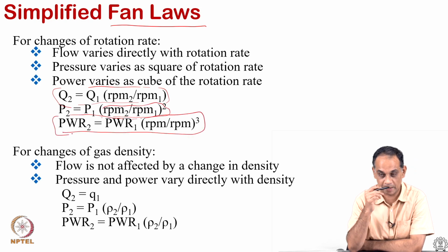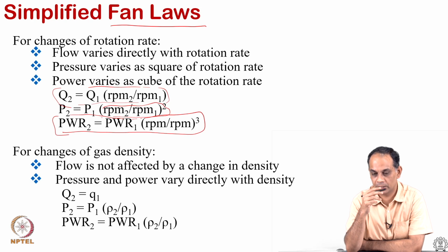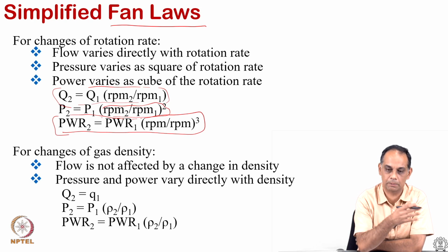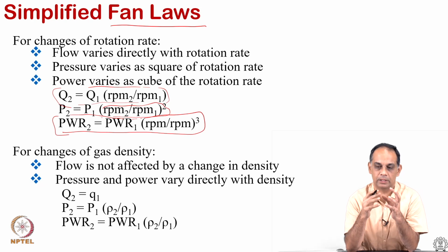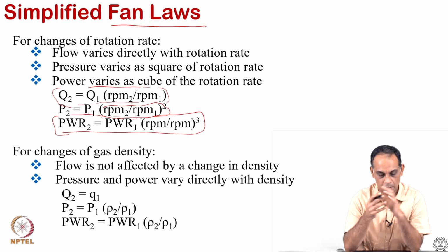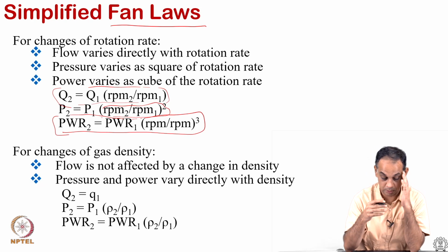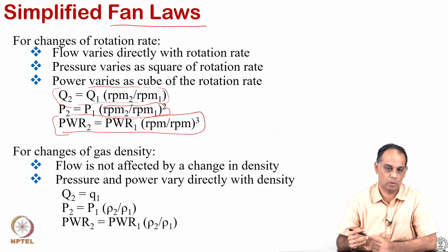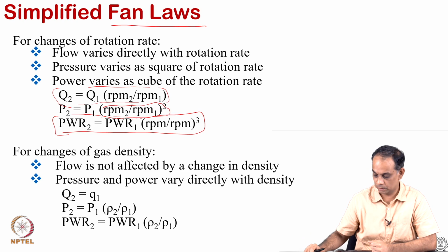So you can use the fan laws to assess whether the given fan is going to work for you or not, using the fan laws and the pressure drop and heat transfer, and that completes the fan heat sink model combination with the help of heat exchanger theory. And also one can account for gas density and so on, and that can change the scenarios.